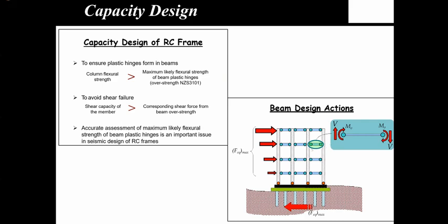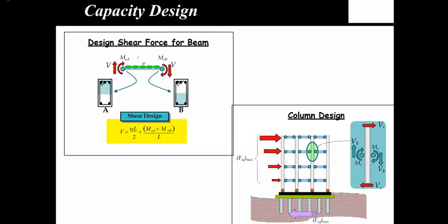And for that, what you need to make sure is that you avoid any shear failure in the beams, and also you avoid hinging in your columns apart from at the base. You can't eliminate the hinging at the base, which still is a stable mechanism, right? So how do you design the shear in the beam so that you avoid shear failure? One thing, you assume both ends of the beam have plastic hinges, and the corresponding overstrength moments are, say, MOA and MOB, right? That's purely due to earthquake demands, and on top of it you have gravity load, say W.